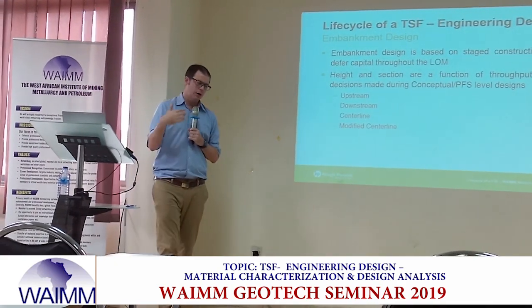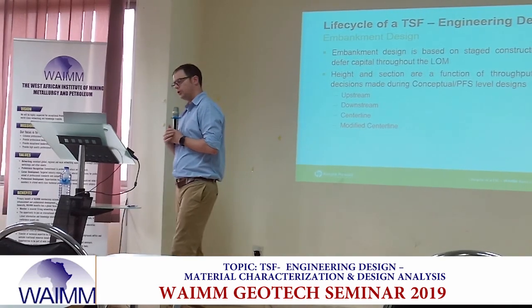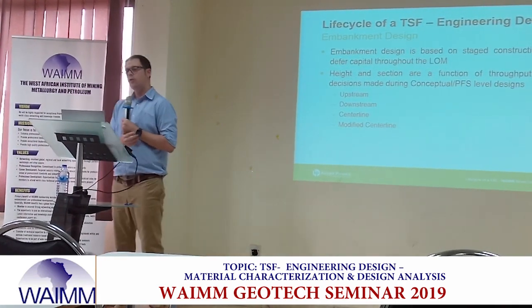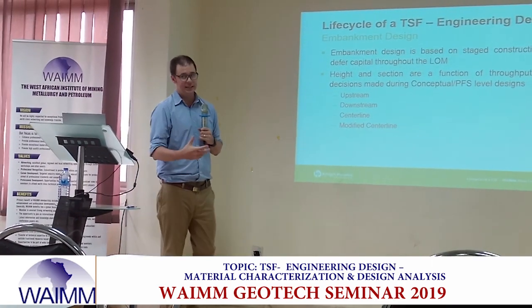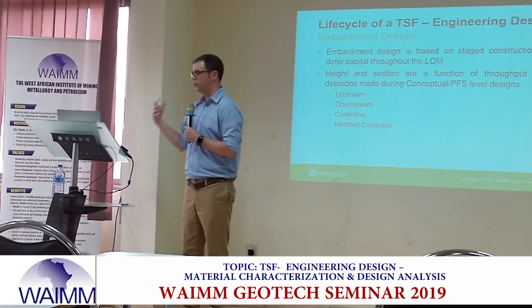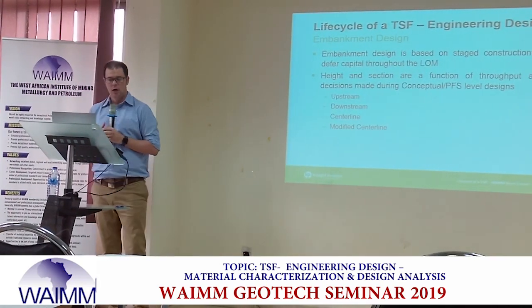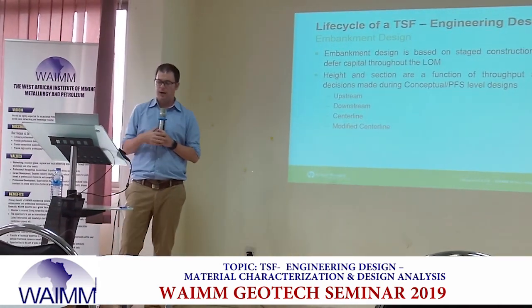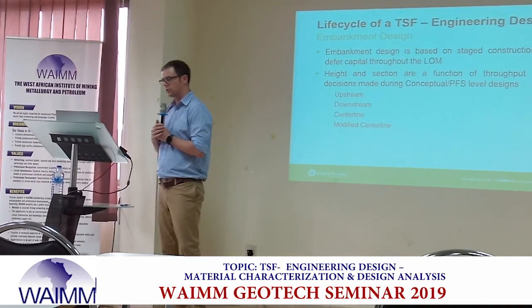Okay. Then we also want to look at the height and section that we'll be developing it to, and those decisions should be made throughout the process. In conceptual design, we should have an idea, and then we refine that through our PFS and our detailed design, detailed engineering. Do we want our facility to be upstream raised, downstream raised, centerline raised, modified centerline raised? We'll show some photos and talk about those in a minute.